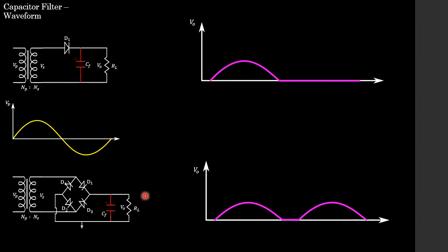And what I've plotted on this slide, students, is we have the primary side voltage of our transformer, which we can see is a very nice sinusoidal input, that's Vp. And here I have the output voltage plot from the rectifier part of our circuits. So that's the output voltage here and over here for the various circuits.